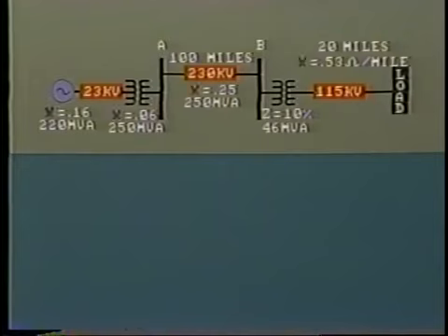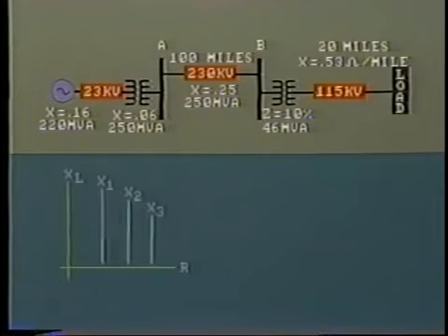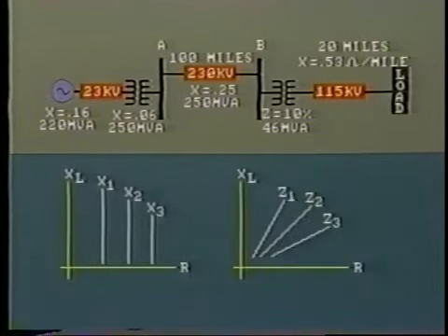Incidentally, the drawings will more often indicate the per unit values for X, that is, reactance, instead of Z impedance. This is because, from the point of view of fault calculations, most of the impedance is made up of reactance. Also, it is more correct to arithmetically add reactances than impedances, which may be at different phase angles. Either way, the difference is not significant. Hence, the use of X values is quite acceptable and satisfactory.